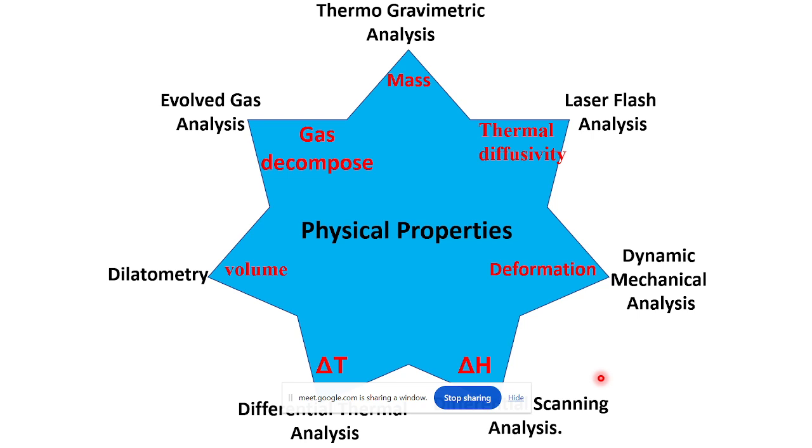And also for DSC, the rate of increment of temperature is very much important. If you perform the same analysis at a higher rate, you will get Tg at a higher temperature, and also your melting temperature will be shifted to the right-hand side if you perform the analysis at a higher rate, 10 degree or 20 degree centigrade per minute.